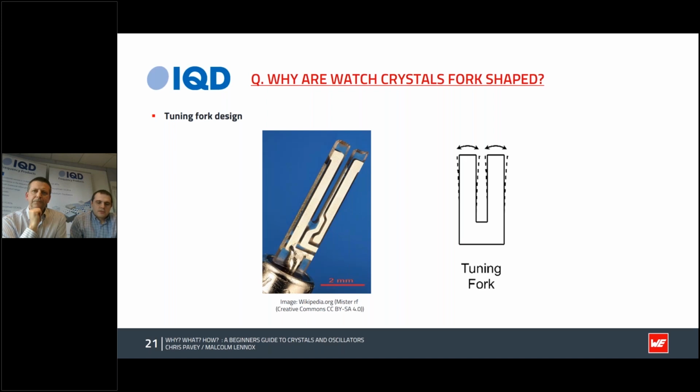Watch crystals operate in the flexure vibration mode. The working principle is the same as that of a metal tuning fork. The two tips will vibrate at a certain frequency. This frequency is defined not only by the mass of the tips, but is related to the mechanical dimensioning of the tuning fork tips, which includes all 3 dimensions: the length, the width, and the height.